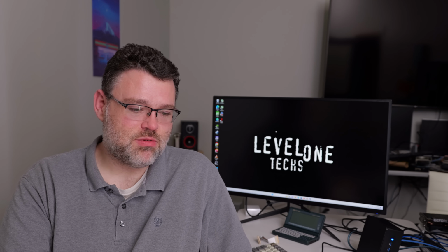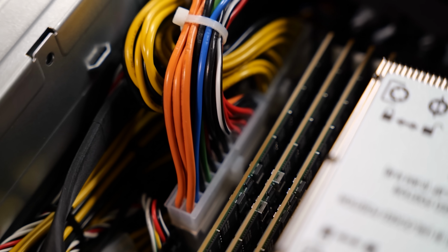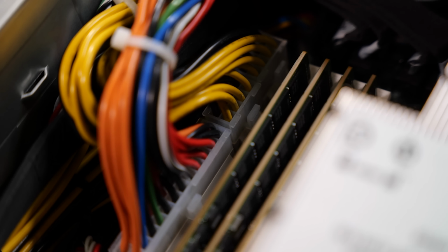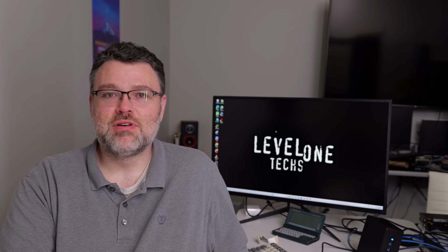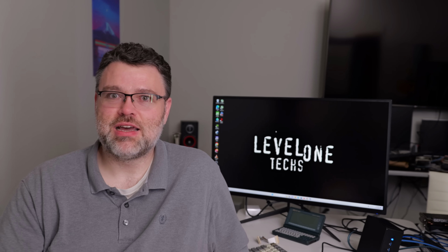It's all about PCIe lane routing. Sometimes you got to do that with a cable. Sometimes you got to do that with a printed circuit board. Sometimes you got to do that with a combination of a cable that goes to a printed circuit board and then turns the cable back into a PCIe slot, because you physically need to route devices somewhere that you can physically cool them. So you got to get creative in server design. So Oculink. You also don't have a lot of room on motherboards for physical connectors or slots. And so again, Oculink saves the day.